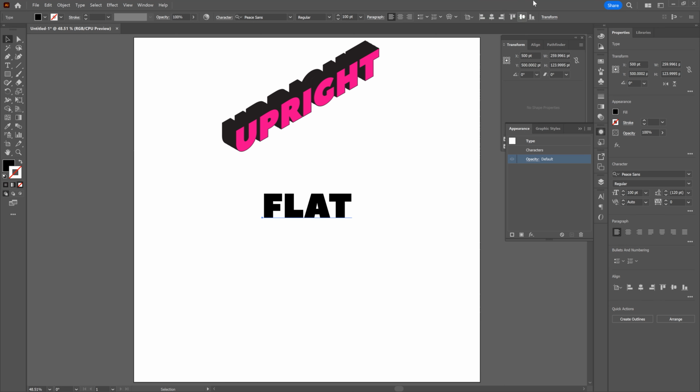Now that we've got that done, let's go ahead and open up our transform window once again, select our height, and let's enter once again 86.602%. Let's enter a shear value of -30 and 30 degrees. Note right away, you've got your isometric type from bottom left to top right, which is flat.